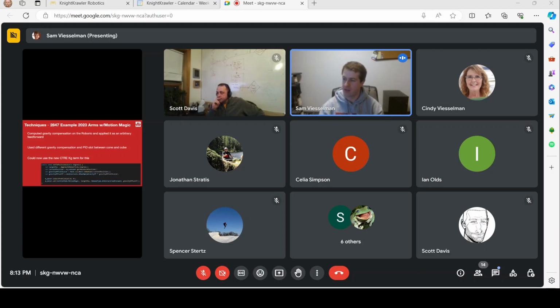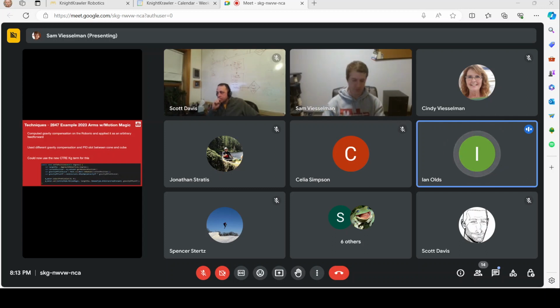Could you share what you're controlling, and maybe there's a bit more info? We're controlling the angle of the shooter, very similar to what Scott's talking about. But with the encoders, we're just doing it on a reset basis: hitting a limit switch and resetting the value to 0 at the bottom, and then as it moves up, we just check the Spark Maxes. We've got an encoder on there that's not absolute. We just check that, and so we're just controlling the position there. So we don't need a PIDF, but in a use case we probably would like that and the ability to do that.